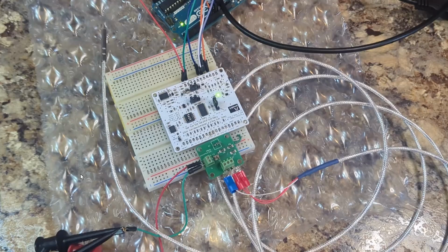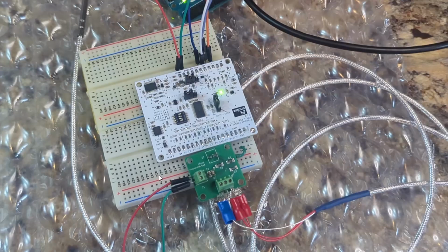Okay, here's an example setup where I have a 3-wire RTD sensor. You can see the end of the probe right here. And I have Anabit's Precision Logger, which is a board that has a 32-bit ADC. It has 5 differential channels, 10 single-ended channels, so I have it configured for a differential measurement. And it can make very accurate measurements at high resolution. And then I'm just using an Arduino Uno with SPI communication to read the value of the ADC. And then I'm using the IEC standard to calculate the final temperature.